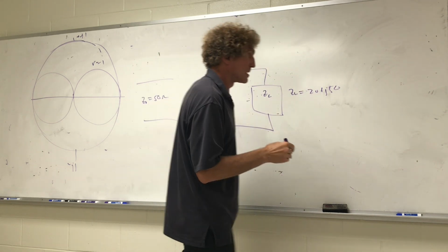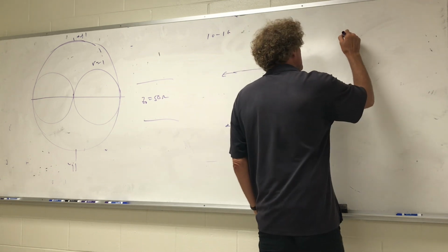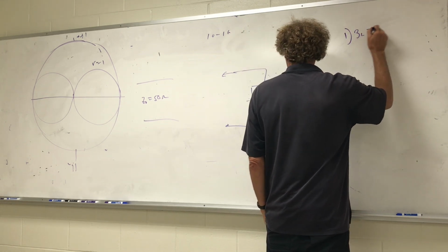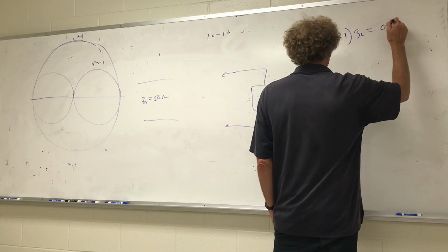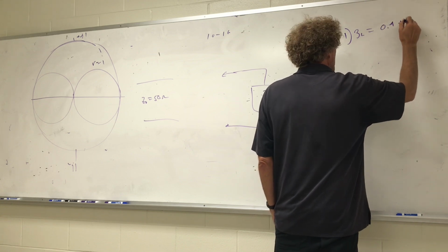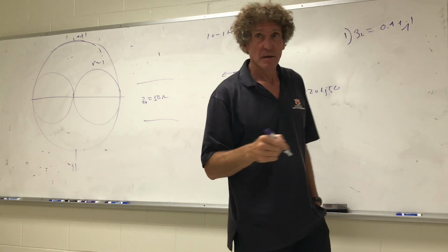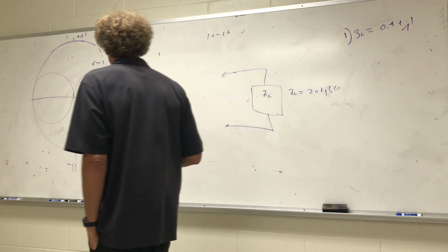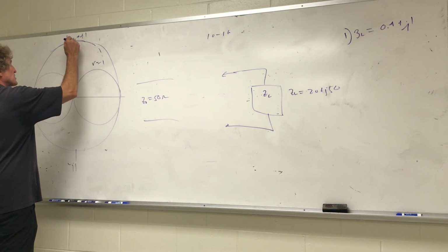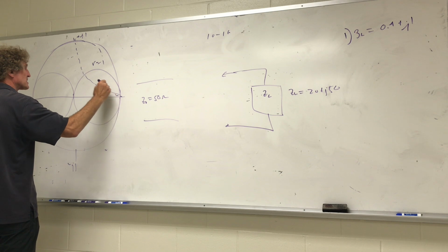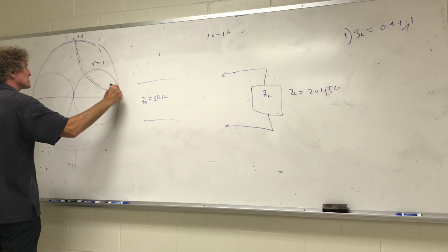Okay, so here's our Smith chart. First thing we get is normalized ZL, since it's 50 ohms, that's going to be 0.4 plus J1, correct? Yep. All right, now let's locate that. Make sure you can see this. Here's the plus J1 circle, or I'll call it trajectory.